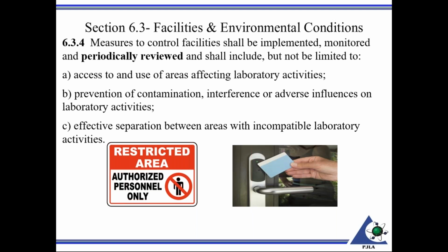I always say that the UPS man can't come freely walking in a calibration lab and open the doors without having some sort of controlled access. It should be effective separation. Perhaps you're doing precision weighing, you have microbalances. That should be away from any area that perhaps is producing vibration, perhaps any sort of loading dock or high traffic area.